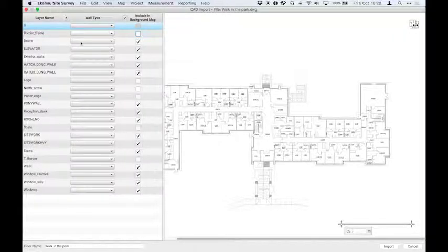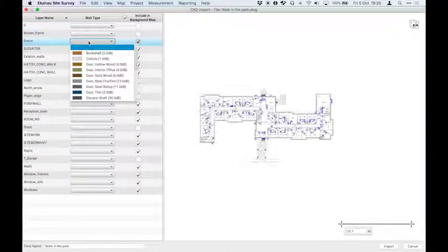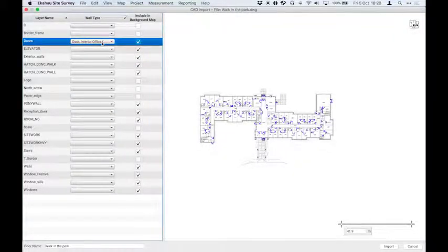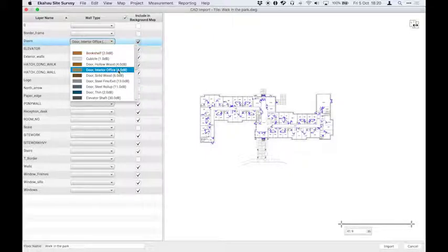Now what we'll start doing is mapping attenuation properties to some of these elements. So doors, for example, you can see how they highlight in blue on the right hand side. And we'll map these to interior office doors. And you can see this had a dB loss value here of 4. So this means 4 decibels per meter is the attenuation properties of this.